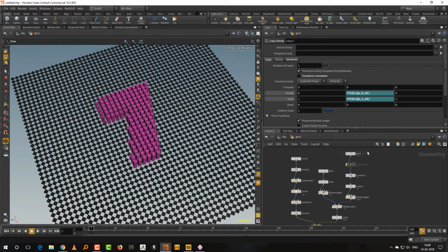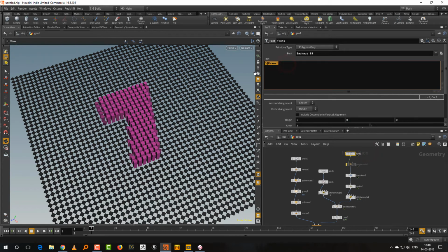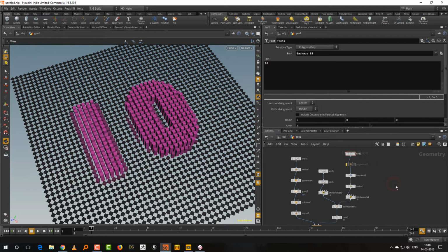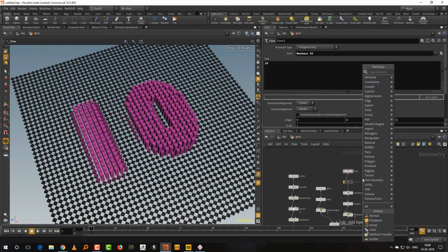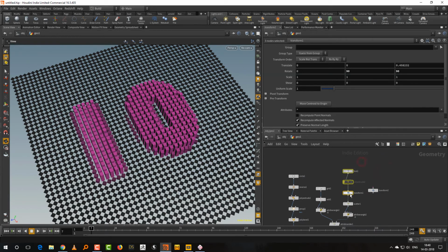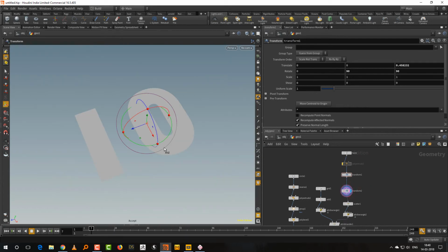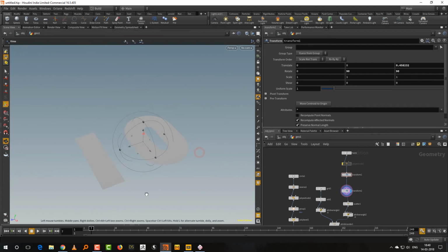So what will happen is, if I make it, say, 10, like a fixed value, and I take a transform, and let's say we'll just animate it a little. I'll come in here and push this down a little. Now the way to animate it is you keep Alt pressed and click in the value, so that will set a keyframe. And once you've set a keyframe, you can turn on this button which says auto key. Now I can, let's say, come ahead to about 17. We'll take it down to 0.